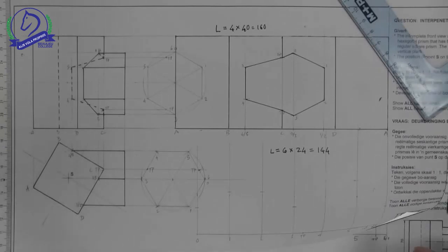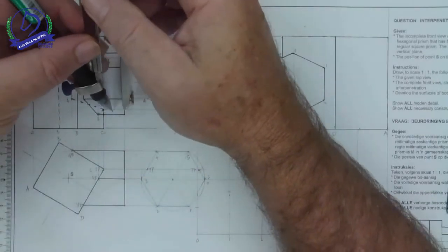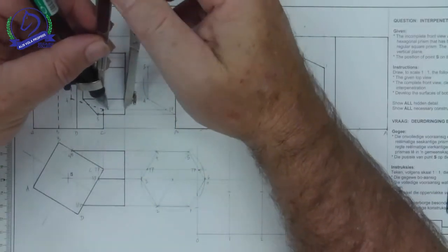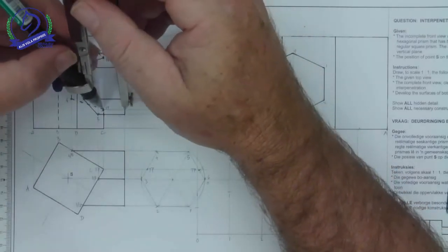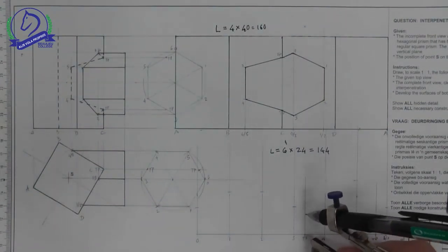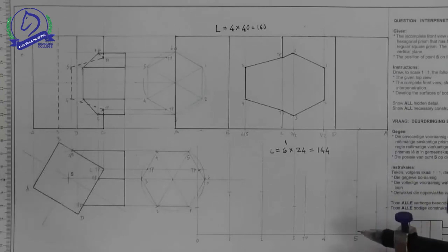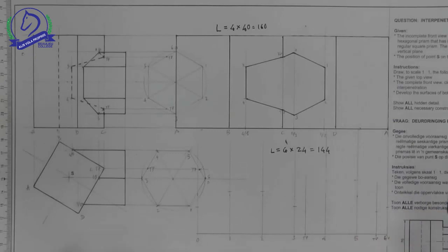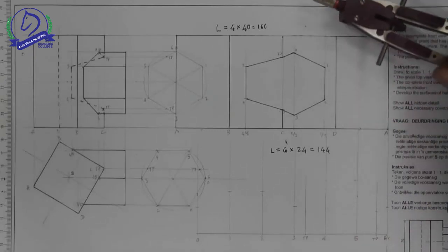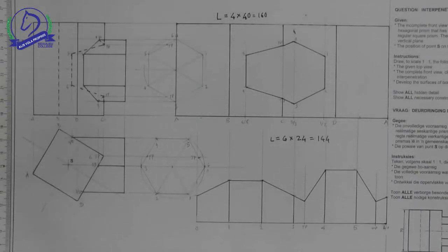Drawing the vertical line. Now take the measurement. Generally come and take that from the front view is your best option, just to make sure you get used to that, and mark that off. There we have all the points, and we can join them up in our outline. There is the completed outline view of my branch pipe development, and that is the end of drawing 85.